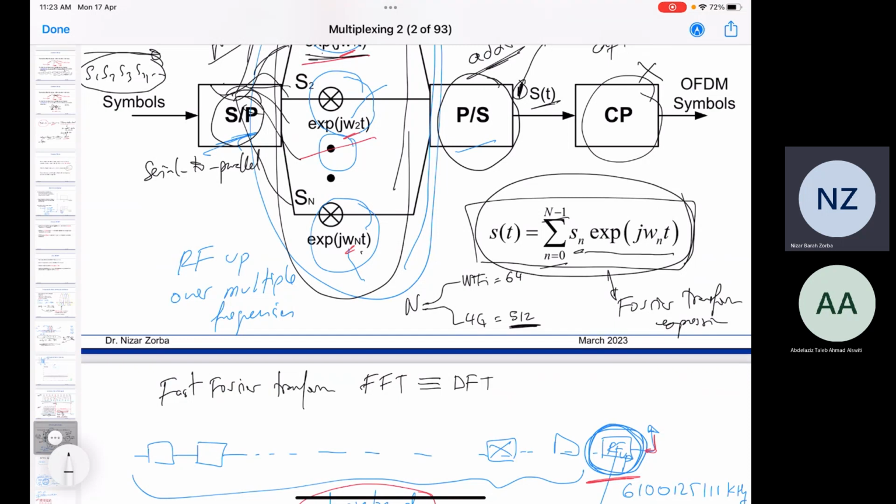So here the DFT and the FFT are exactly the same, not an approximation, 100% perfect. The FFT works if and only if there is a constraint: N has to be equal to 2 to the x. So this is a kind of restriction on the input signal. If you want to use FFT, your signal length has to be 2 to the x. Does it sound familiar to you? Ali, does it ring a bell on something that you have seen?